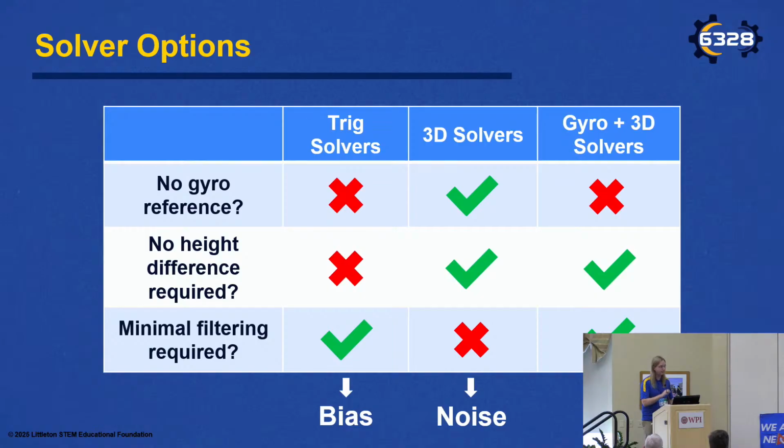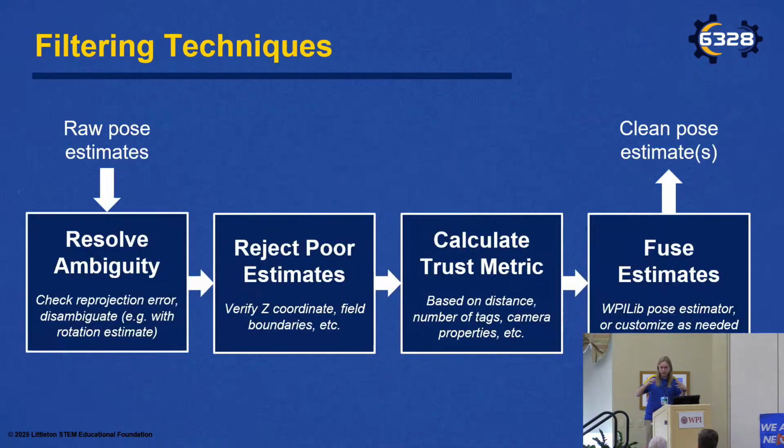So there's less variation in the individual estimates, but particularly as you get further away from the target, you'll find that those estimates are consistently offset from your real position. Both of those are possible to deal with in appropriate moderation, though generally we find that noise is easier to compensate for than bias.